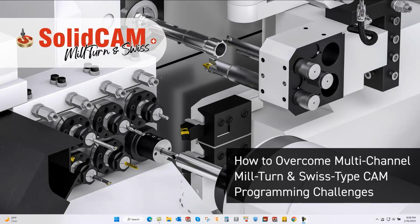Sure. And now, the machine you were demoing all this on was a Swiss style machine. But for lathes that have live tooling, but maybe aren't quite as advanced as a Swiss, for example, one with a y-axis, another with a positional b-axis, how does this software support this type of machine configuration? Well, the way I like to categorize Swiss is really just a more advanced mill turn, but on smaller parts. So it works almost identical. Now, the difference would be a little bit in the setup, and that's it.